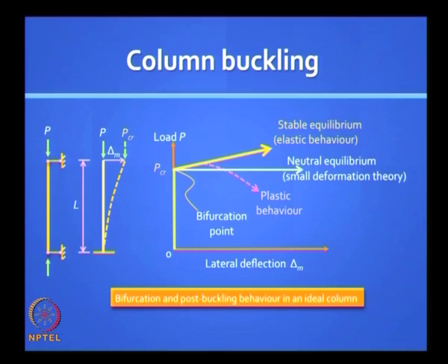So these things are well known. That is called large deformation analysis, which you do not normally study at an early level. But in elastic stability, you get a solution like that. Now if the two ends are simply supported or pinned like this, the buckle shape will look nicely symmetric. And this is a standard case which Euler explored, and this is called the Euler buckling load for the standard case, where the solution is pi squared EI by L squared.